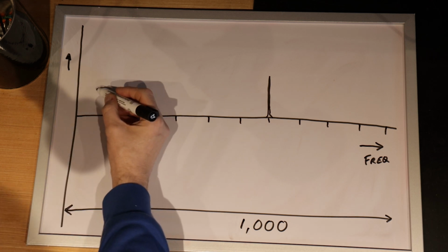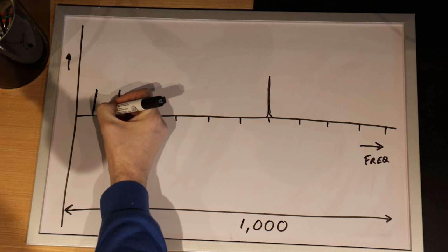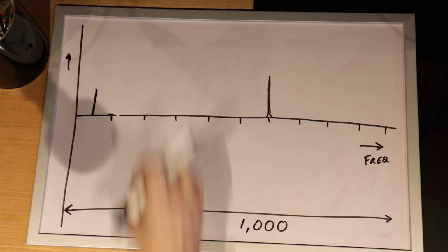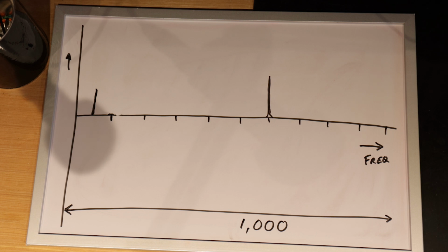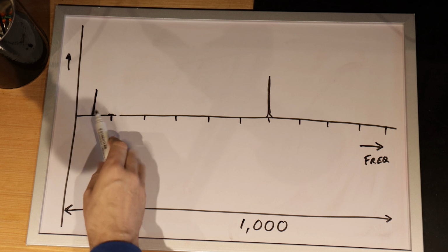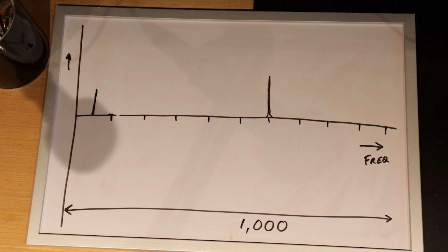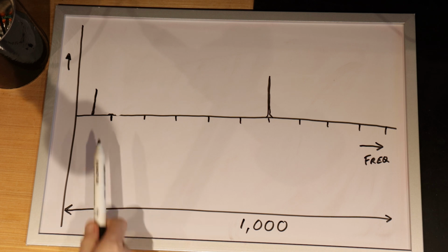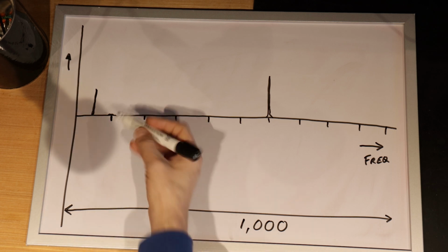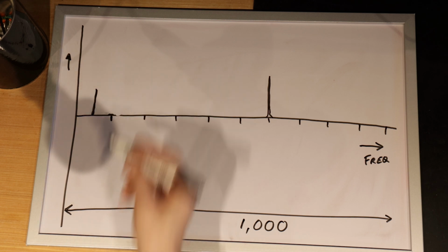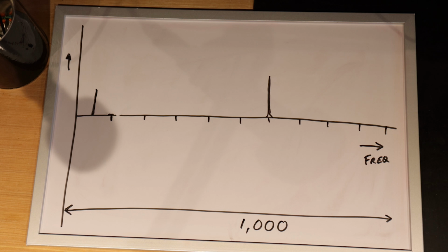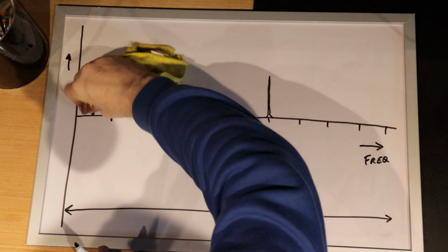If the signal was at 60 or 50, then that would allow us to know that the hum is getting into the system at a slightly different location. If it's straight mains hum, you're looking at 50 or 60. If the hum is being induced later on, after the signal's been rectified, then it would be 100 or 120. So that would allow you to know whereabouts that's happening. That's just one thing.